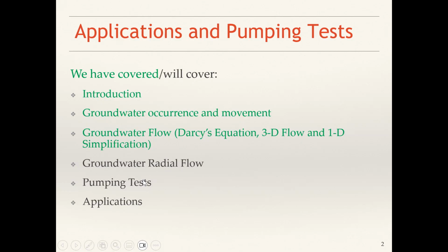This pumping test is a test that we do to find out the aquifer properties. Properties like the hydraulic conductivity, then the specific storage, and anisotropy. So this kind of aquifer properties can be found by using this pumping test.